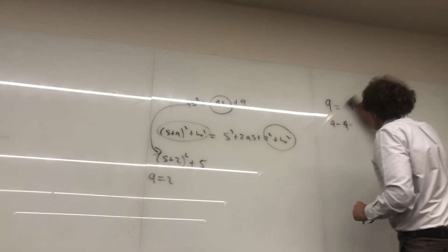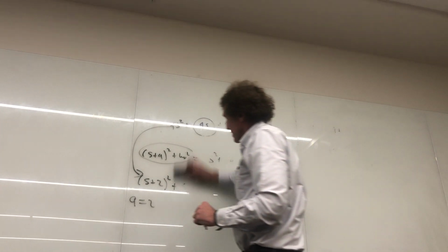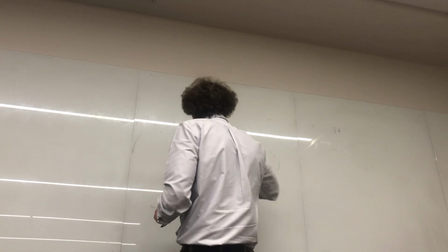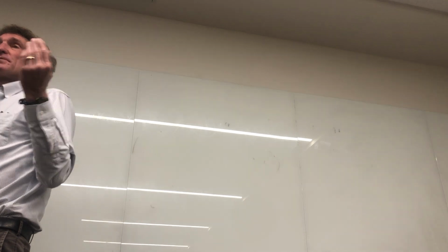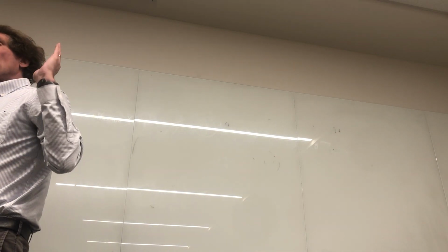Now, circuit analysis. I want to go through this with you. When you're talking about no initial conditions, those are the trivial problems. You just put in an equivalent impedance for an inductor, which is SL, and for a capacitor it's 1 over SC, and just solve it the way you would any other problem, right guys?